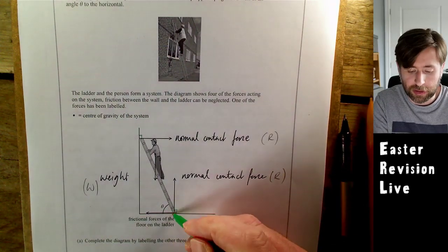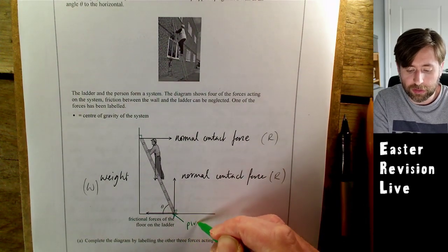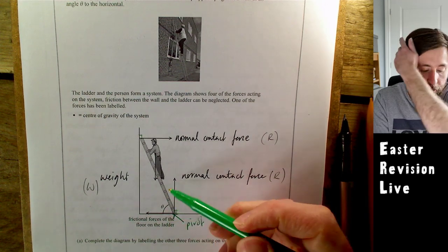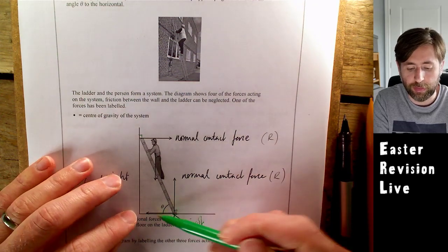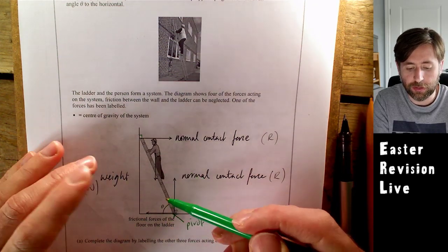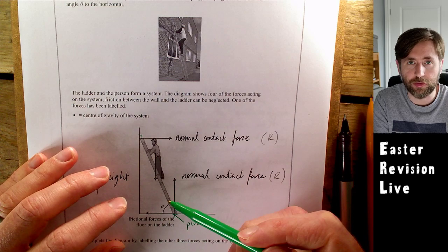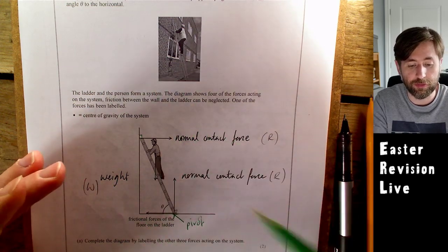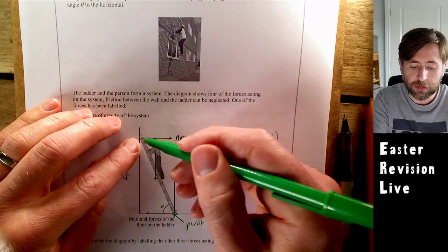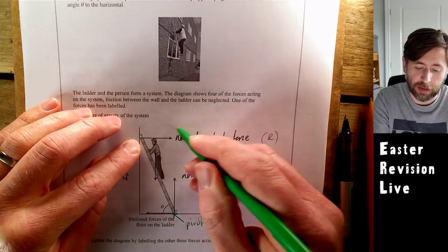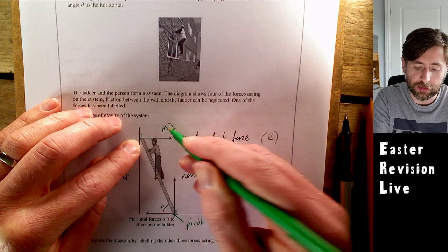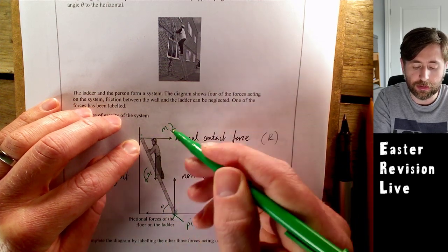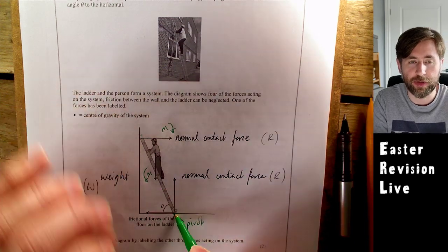Here's our pivot down here. You could add two things on this if you like. These two forces are acting at the pivot, so they don't cause a moment. They are forces that are important for balancing the thing in terms of Newton's laws, but not in terms of the principle of moments. Now this force is acting to turn it clockwise, and this force is acting to turn it anti-clockwise. So these are the only two that we need to consider around this pivot.